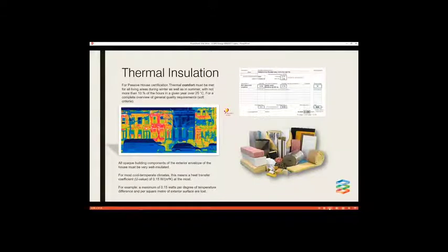So the criteria I've put on the slides here so that you can read through it. I'm not going to read it verbatim because I'm pretty sure you all can do that. But what I do want to point out is that in the image on the left-hand side, you can pick which building has been retrofitted out of the row of housing through the thermal imaging. It's quite often a slide used in training. So the one that's insulated is the one that's blue.